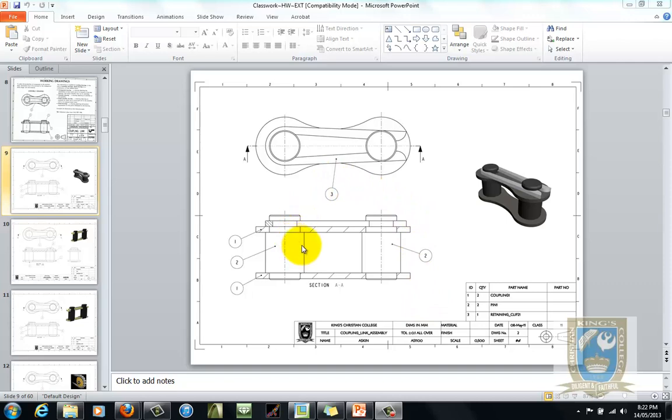First of all, there's only enough views chosen to show the relationship between the parts. Remember that the major focus for any assembly drawing is to show this relationship. Relationship means basically how do the two parts fit together. And if we look down to this front view, we've actually got a sectional front view. So the line AA coming through here. Anything behind the line AA has been cut away, and we're looking in at the front view at what's remained.